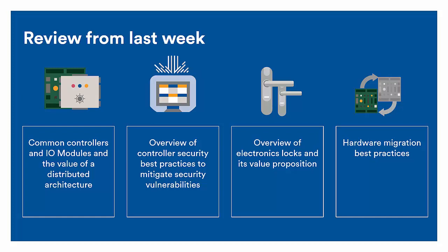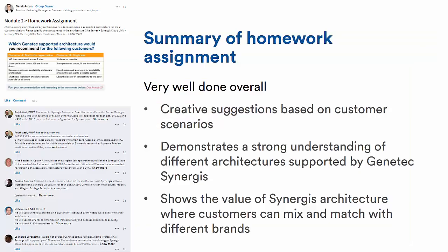We then went through a comprehensive approach of the different electronic locks that are supported by Synergis, like Wi-Fi, wireless, PoE, RS-485, and even data on card systems. After blazing through each lock architecture, we ended off with some hardware migration best practices. We introduced the Mercury M5 and MS Bridge product as a cost-effective alternative to a forklift migration, and then we ended off the module with a homework assignment.